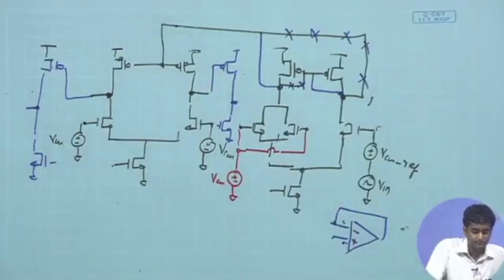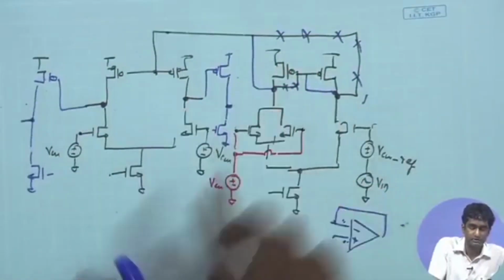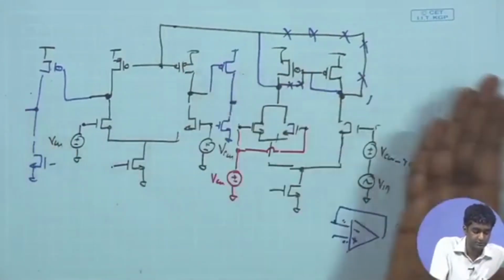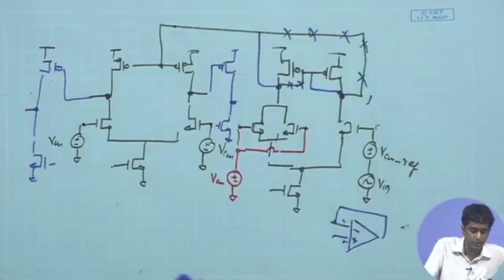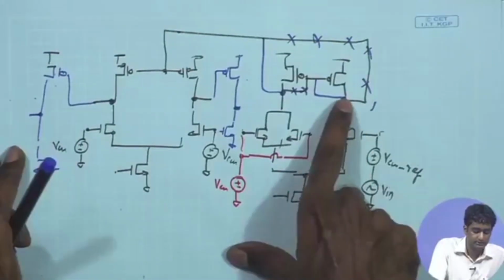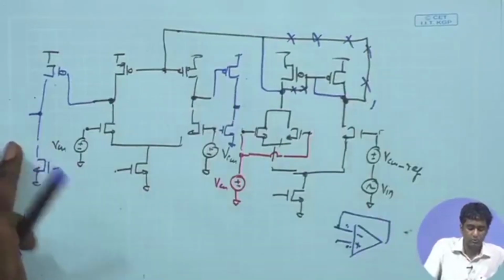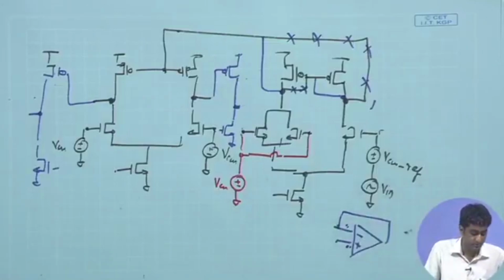So if I use the current mirror load for the common mode feedback for the two stages together, then the loop gain is pretty large, so it is GmRo cube, and it may lead to more instability. The other serious issue is that all these three nodes, the output of the first stage, second stage, and the common mode output, have almost similar pole magnitudes. So compensation becomes a little more challenging.